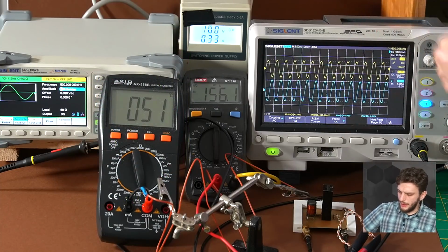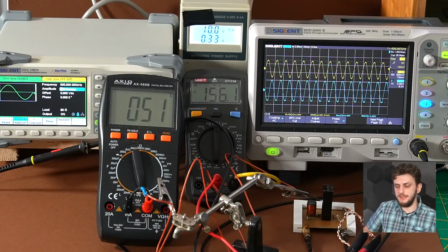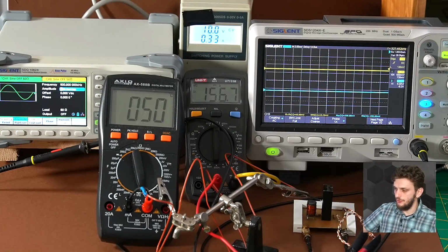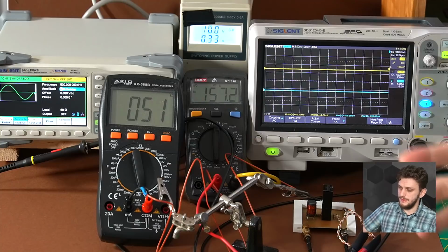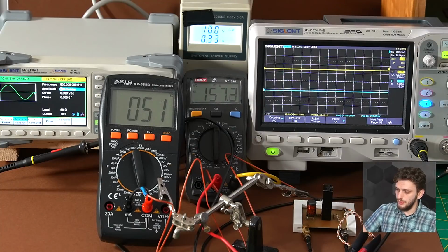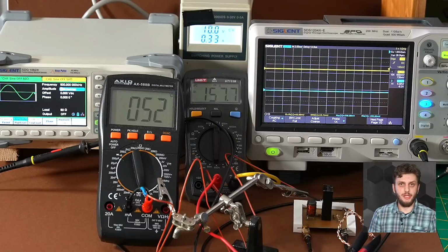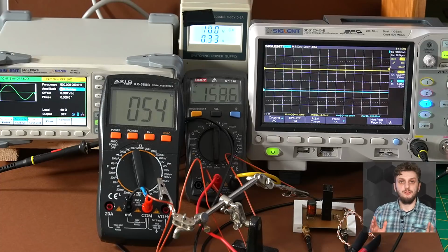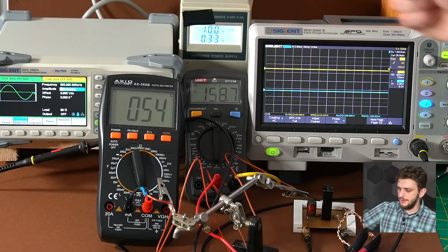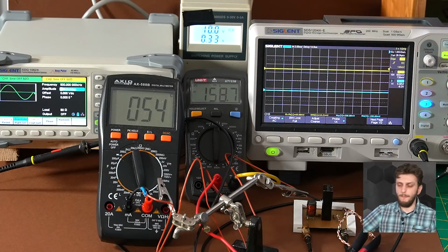Now, we can also look at what happens with the amplifier if we turn off the signal. Right now the signal is off, and current consumption stayed roughly the same, but since there's no more power being delivered to the load, we should be seeing an increase in temperature, since now all of the consumed power is dissipated on the transistor. As with any thermal behavior, it takes the time it takes, but we can see that the temperature is now slowly increasing. We're at about 54 degrees and it will probably increase a bit more.